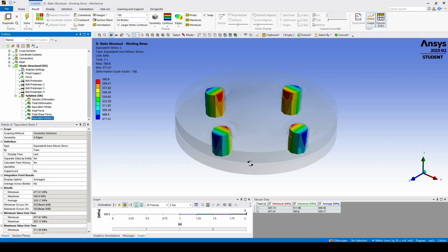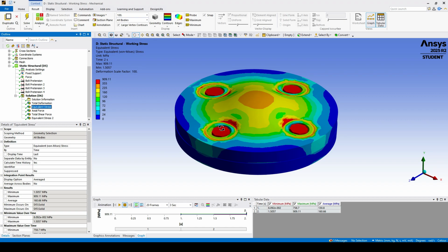When we tighten a bolt, we don't simply clamp two plates together, as you can see. The bolt is stretched like a spring, as you know, creating a preload that holds the joint together. At the same time, the bolt experiences torsion because of the applied tightening torque. So during assembly, the bolt is subjected to two different stresses: axial tensile stress caused by the preload itself, and a torsional shear stress caused by the tightening torque.